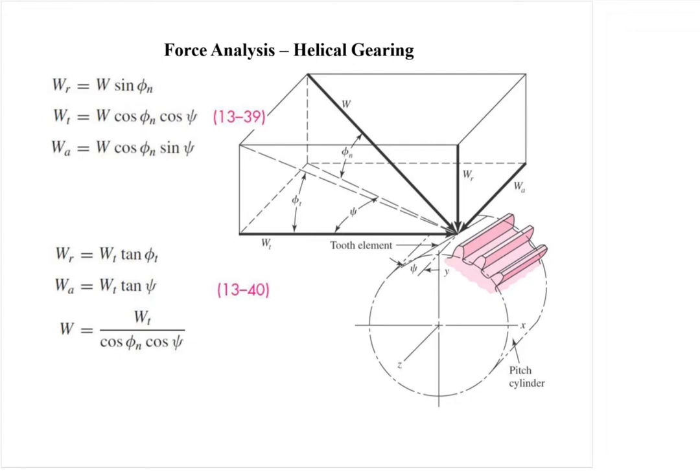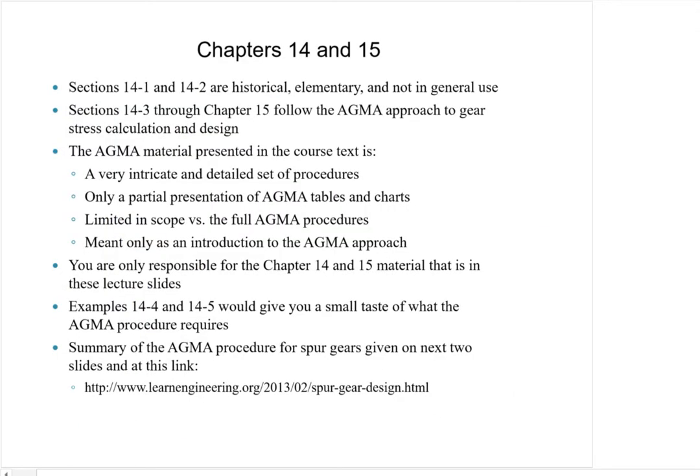Practically speaking, for any kind of force analysis you need to do on these, I would again use FEA. Use FEA if you need to do something like this. But FEA is not going to pick up the manufacturing variations and all that sort of stuff. So sometimes a direct inspection is what's best.